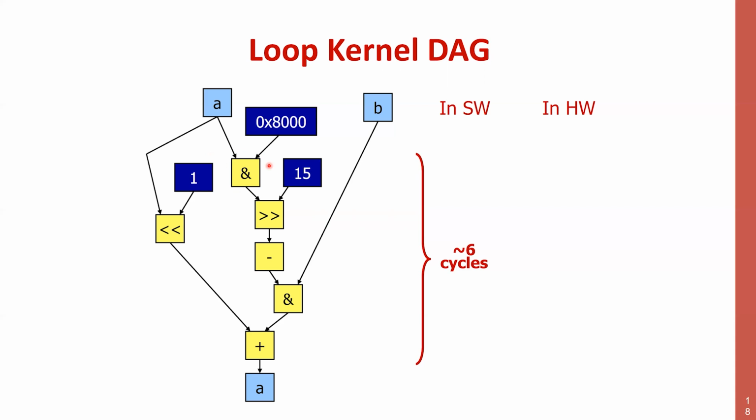So you are going to tell me that I speak transistors. I should not, because this is a computer science department. So I'll tell you that a NAND gate, if you don't know, has 4 transistors. And I also tell you that I don't care if it is an AND or a NAND, because generally when I'm doing a circuit, if I have a negation here, I don't compute exactly the AND but the NAND of the input. I usually can compensate for it later, because I hope you remember things like De Morgan's theorem and so on. You can play around with inversions and sort of absorb them in the computation.